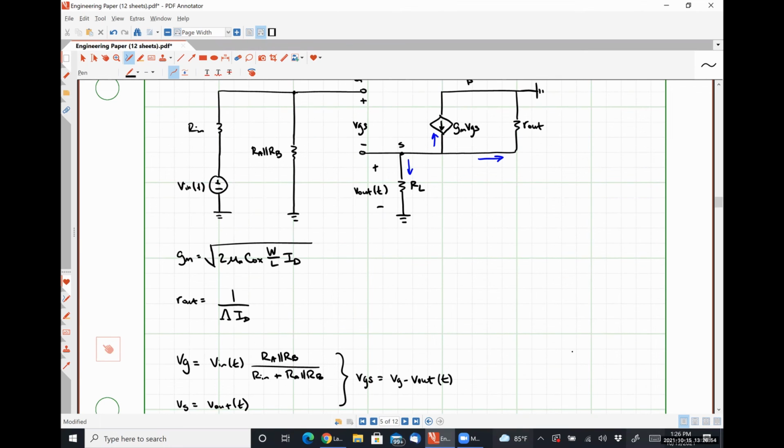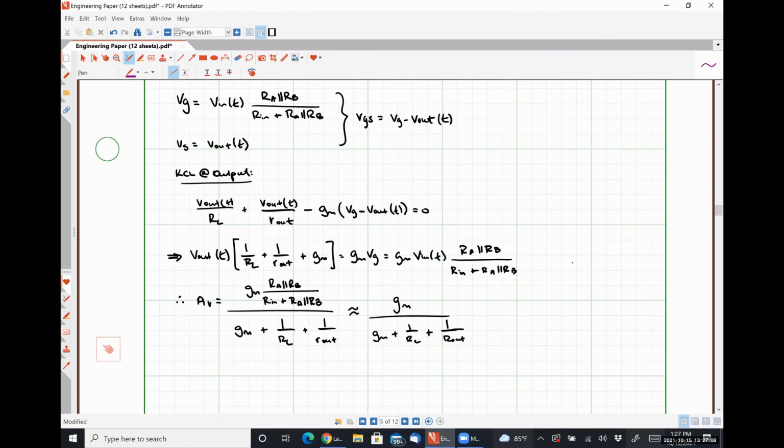It would be parallel with that load resistor RL. Exactly right. So we could just drop this guy in here. Here is RCS. And then obviously, everywhere we have RL, we would replace this with RL in parallel with RCS. That is the only change that would need to be made. It's a lot easier to deal with in the small signal model than it was with the large signal model. Okay, so let's talk about this gain.